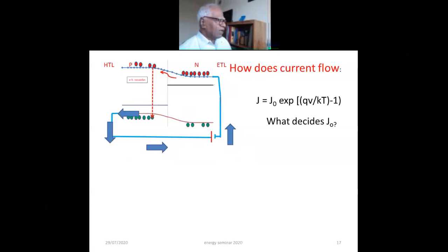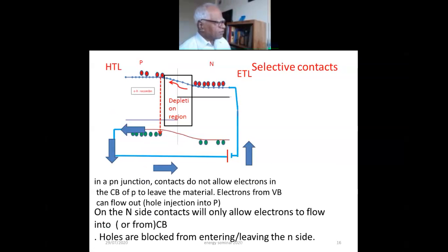So that means by forward bias, this is just all dark. I have applied forward bias, electrons from the N went into the P where they are minority carriers. Now these electrons just cannot go out in the external circuit to make a current. The only way is that this electron has to recombine with a hole.